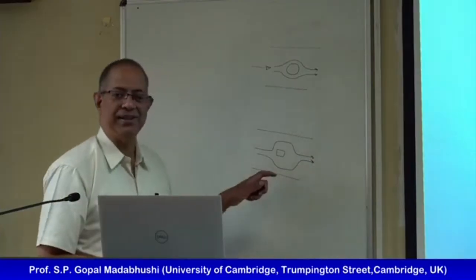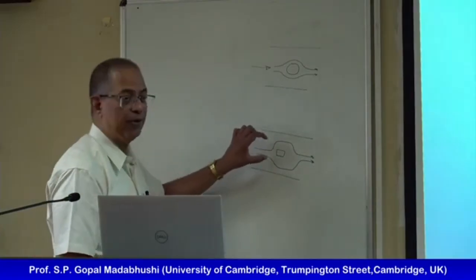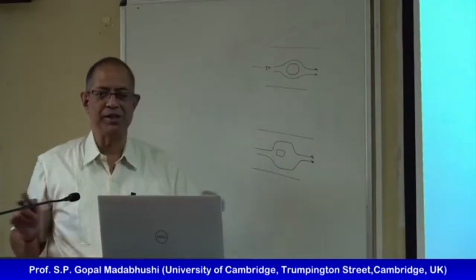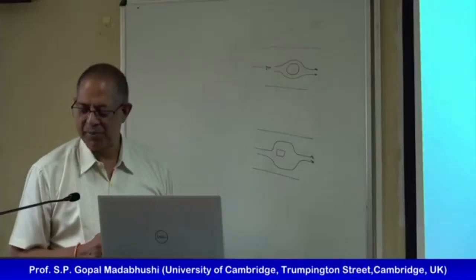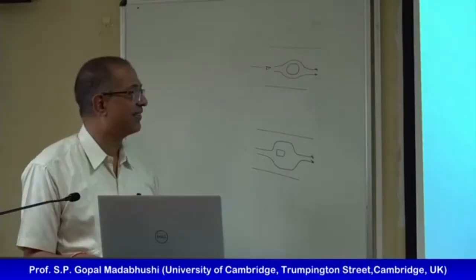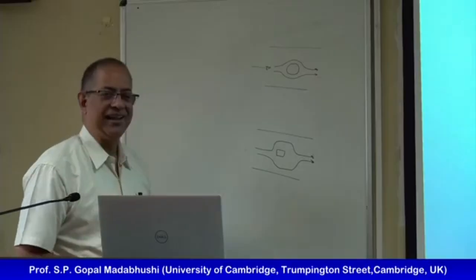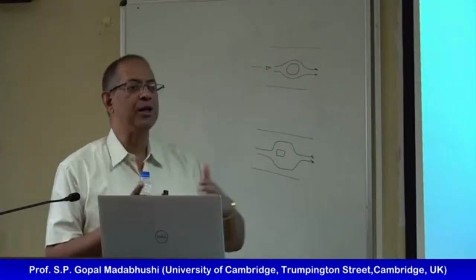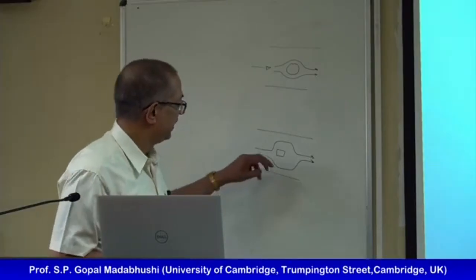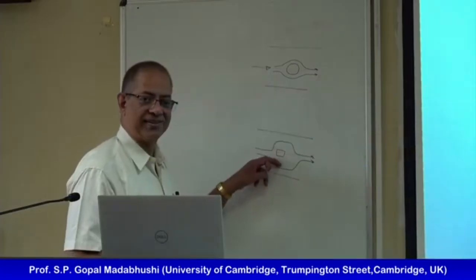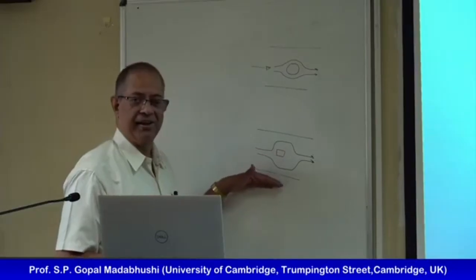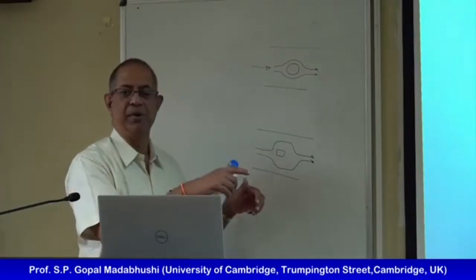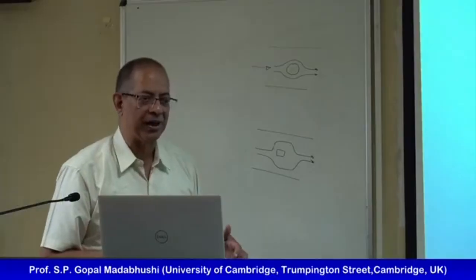So although the bending moment is the same, the zone of influence of a square pile was much wider than the circular pile. At that point, my thought was, really this is going to make a big difference when you have multiple piles, right? If I have a lot of piles, then depending on pile spacing, this zone will overlap with the pile in the next direction, and therefore the soil will have to make even more deviation and it can't flow in between the piles.